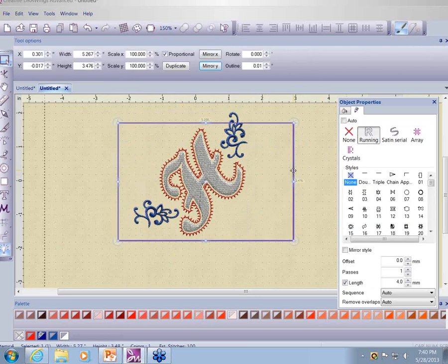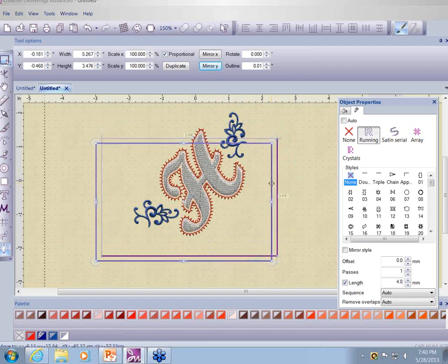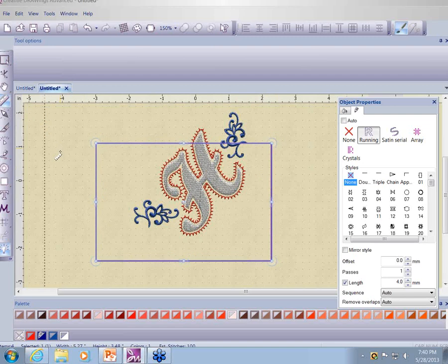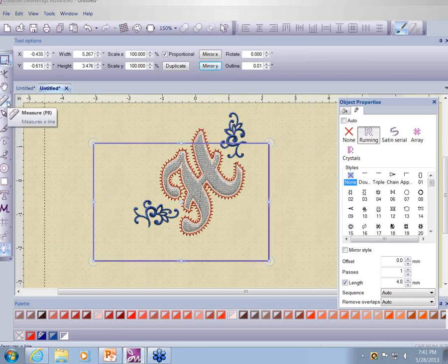My placement line, I'm going to select so I can move it. I want my placement line to be about 3/4 of an inch from my H, this way and this way. And I'm probably too far there, but not enough there. The way to find out for sure is to go over here to my Measure tool, and if I click onto that, I now have a little ruler hooked to my cursor, and I can click on my outline of my H and drag it over to the side here, and this one says it is 0.819, and I'm going to go over here and do the same here. And that one's pretty good. So this side needs to be moved. I can't move it while I have my ruler attached. I have to go back to my selection there. Now I can use the arrows on my keyboard to move that in a little bit. And then I would go back to my ruler, check it again until I get it right.